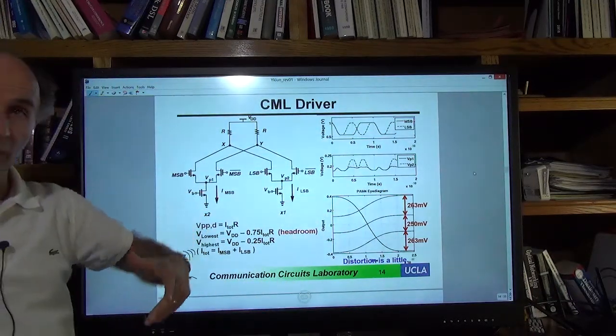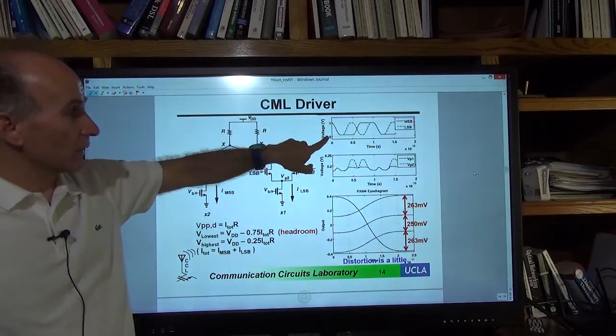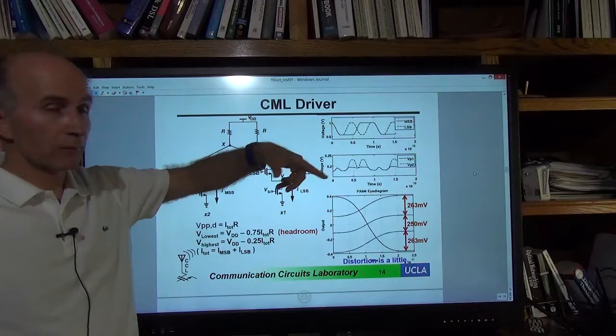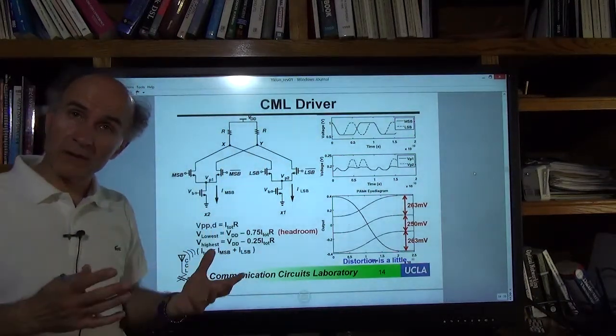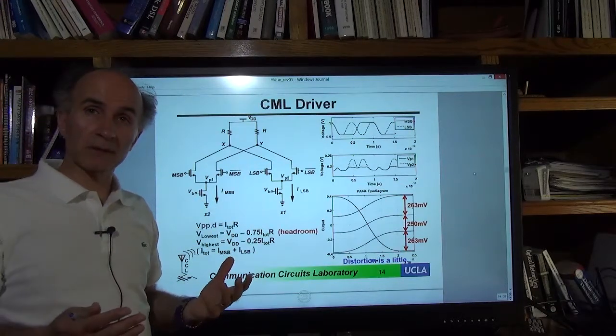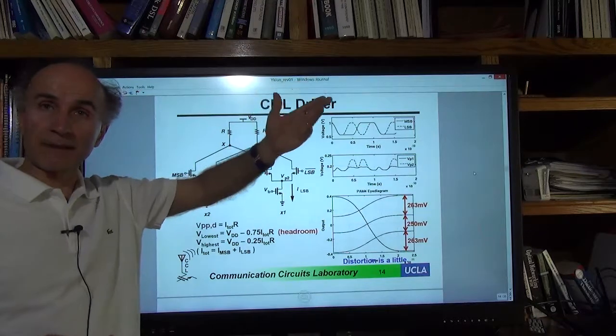But there are other things that you have to care about. For example, look at the resolution of this axis. What we see is 0.5 volts and 1 volt. What happened to all the numbers in the middle? The resolution is so coarse. This is not a professional plot, right? You should have 100 millivolts ticks here or something, right?